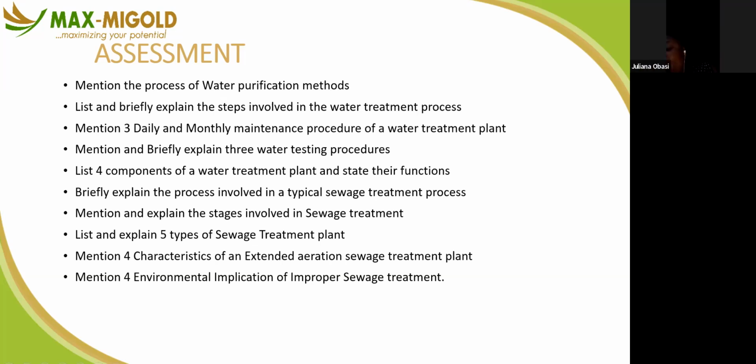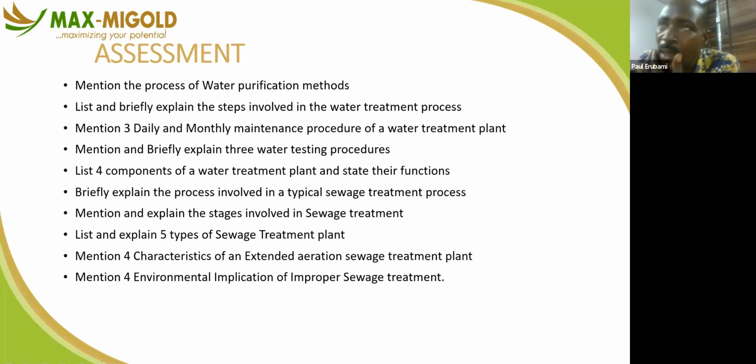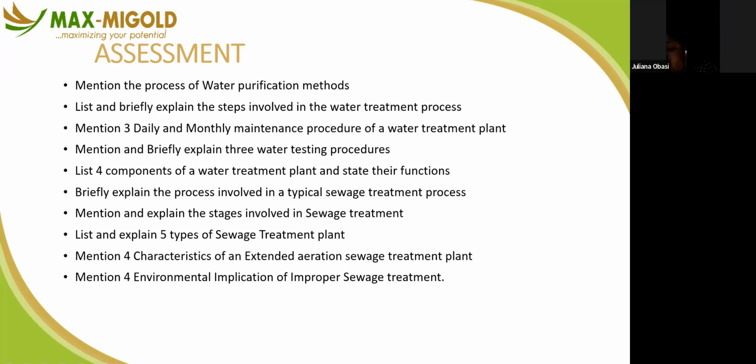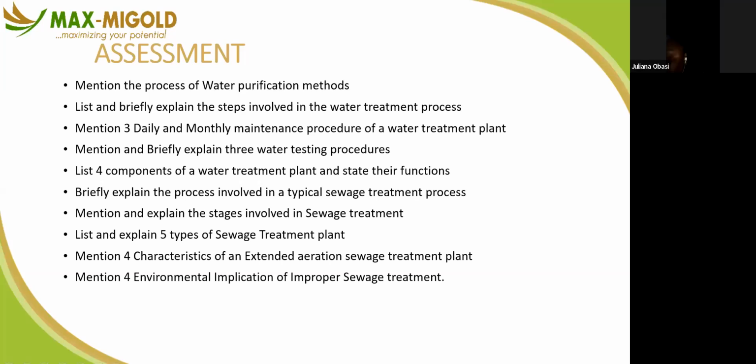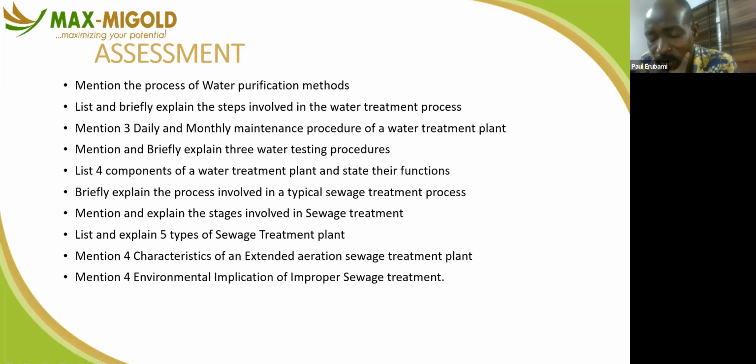Yes, sir. You mentioned water manhole. I didn't get that part, sir. Maybe you should explain it to me again. In a plumbing system, there is always a need for you to create a manhole when your drainage pipe runs more than 15 meters in length. A manhole means that when there is a blockage in the near future, you can open the manhole and clean the chamber, from one chamber to the other, through the manhole. But if it is more than 15 meters and you don't create a manhole, it becomes a bigger issue. Okay, I got it now, sir.